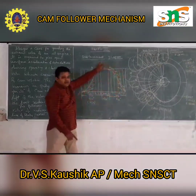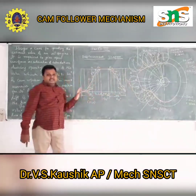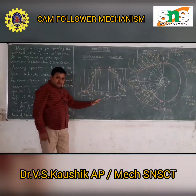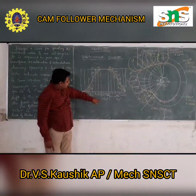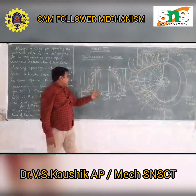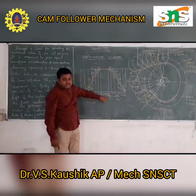So the rectangle will be formed, and you should connect these points as such, and separate this into 3 divisions. The first division is 60 degrees. After 6 centimeters you should draw a vertical line, and the dwell will be 2 centimeters, that means 20 degrees.